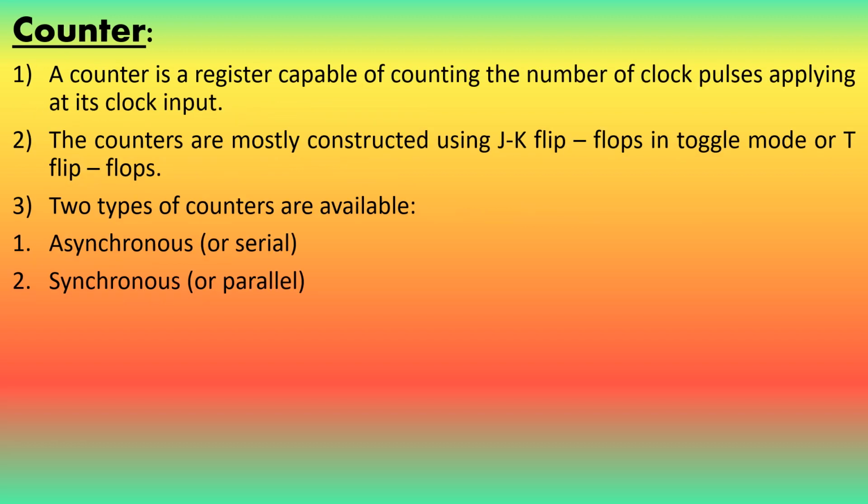Counter. A counter is a register capable of counting the number of clock pulses applied at its clock input. The counters are mostly constructed using JK flip-flops in toggle mode, or T flip-flops. 2 types of counters are available: asynchronous, or serial; and synchronous, or parallel.